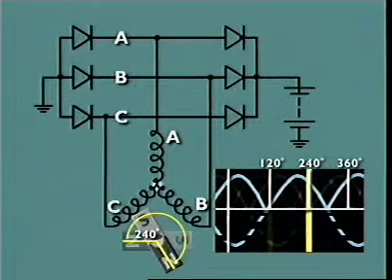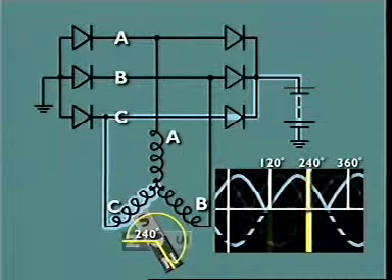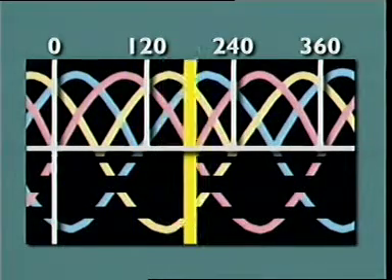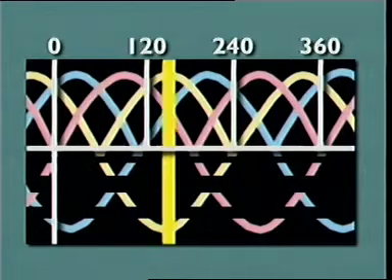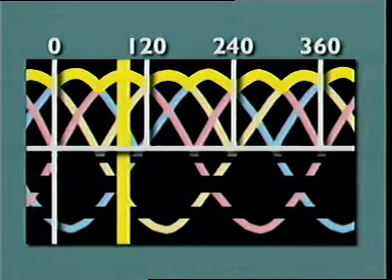When the magnet rotates further to this position, the polarity of winding A changes. The current path then is winding A at star point, winding C, positive diode C, alternator terminal B+, battery positive terminal, battery ground, alternator ground, negative diode A, and output of winding A. As the rotor moves through its various positions, individual phase currents change in magnitude and polarity, but the output current to the battery and the electrical circuits remains unidirectional.